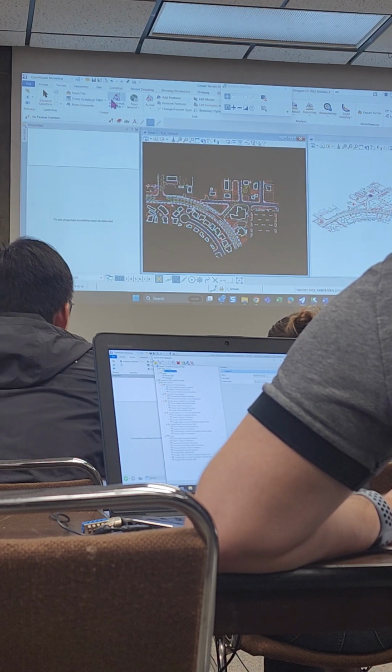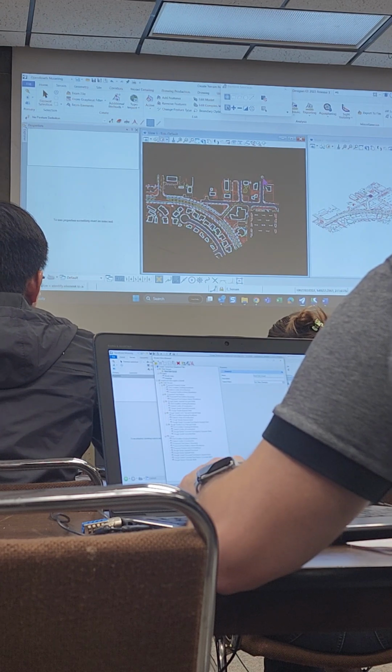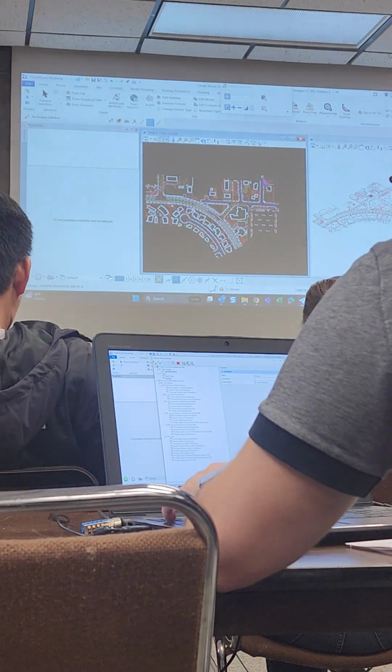And now we can run that graphical filter. I'm going to run this in view 1, I believe. Yep. We're going to go into our graphical filter dropdown and choose from graphical filter. In the settings dialog where it says graphical filter group, I'm going to select the one we just created, which I probably have to scroll all the way to the top for. Select Training. Again, we can run a preview. I can already see I'm missing 2 of my features. So anytime you run this tool, you really do want to hit preview first. We're going to end up adding those in later, but for now, we'll just click through this.